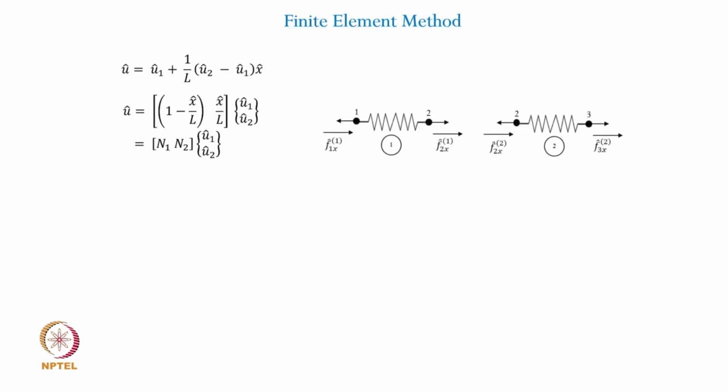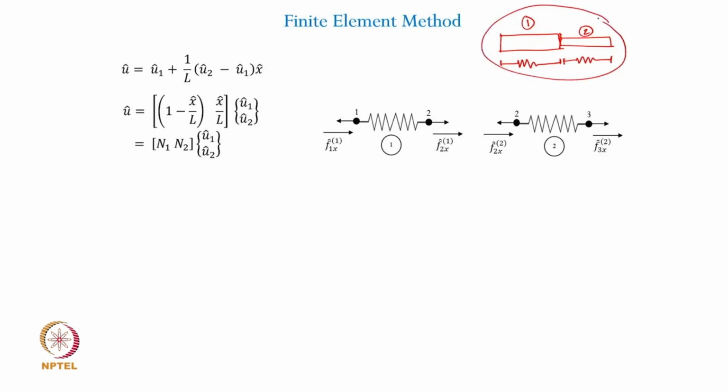And now supposing that this propeller shaft, as you saw as a step shaft, was discretized just into two segments or two elements, like element number 1 and 2, each having constant cross section individually, but one has different cross sectional dimensions as compared to that of 2. If we assume this to be representing one finite element and this one as a separate second finite element, they will have to be assembled together to recreate your original entire propeller shaft.